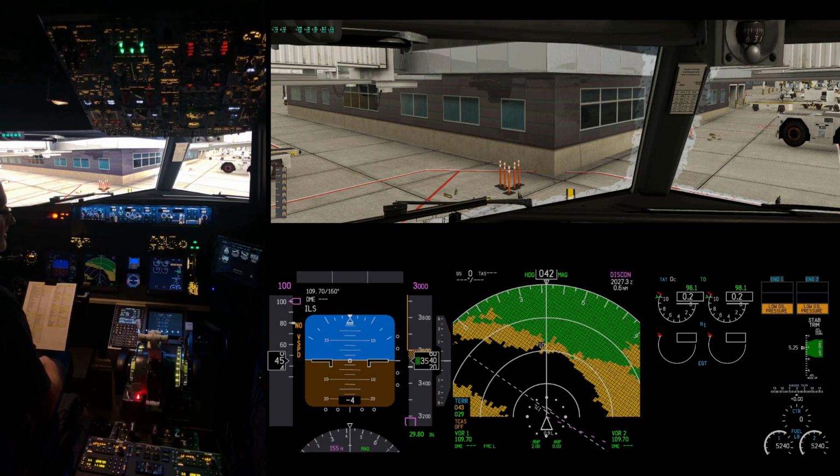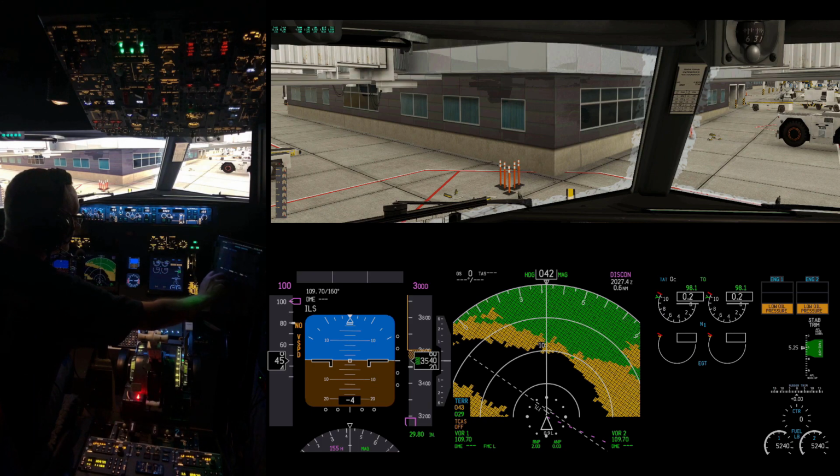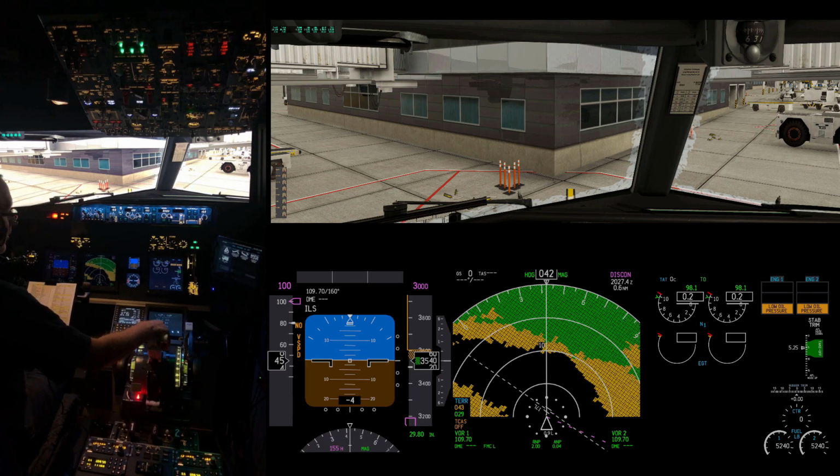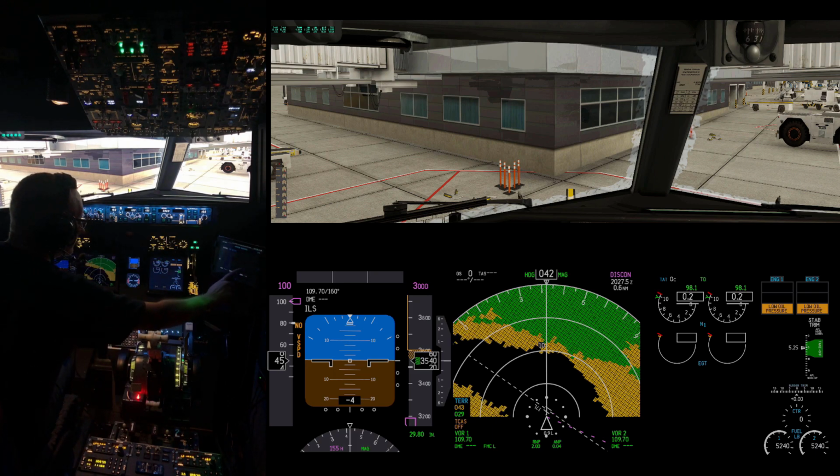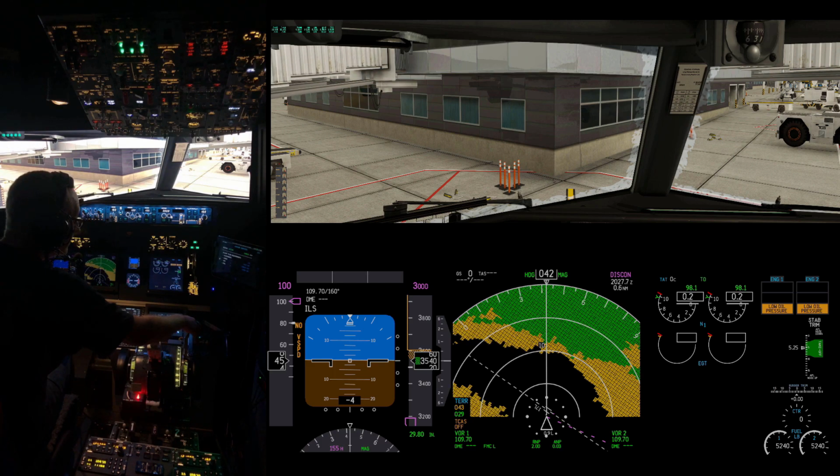Now I'm going to switch over to the EFB and actually load our flight plan into the EFB. So we'll do the loading of cargo, fuel, and passengers. So I go to the second page on airside services, load operational flight plan, and then activate. And it will start the fueling and the cargo loading, and also then the passengers.